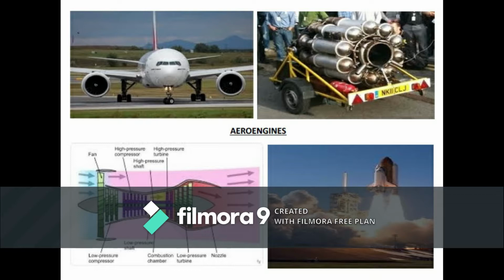So what actually happens in an engine? Especially in an aircraft engine. The piston engine we are already aware of. We provide a fixed mass of fuel and air mixture into the cylinder. Then that fuel and air mixture gets burned. Then heat energy is produced, and the reciprocating motion of the piston is converted to rotary motion, which is provided to the crankshaft.